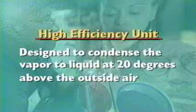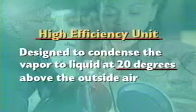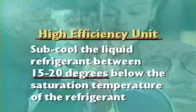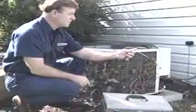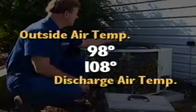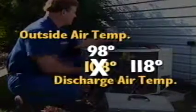Since this is a high-efficiency unit, the condenser is designed to condense the refrigerant vapor to a liquid at about 20 degrees above the outside air temperature, and subcool the liquid refrigerant between 15 to 20 degrees below the saturation temperature of the refrigerant. The outside air temperature is 98 degrees, but the condenser discharge air temperature is only about 108 degrees. It should be at least 118 degrees.